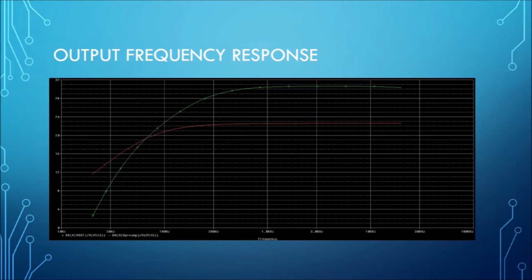As you can see, even though the amplification is very good and exactly where we wanted it to be, the frequency coverage isn't as good as we would like it to be. For instance, the negative 3 dB point seems to be right around 300 hertz, which is a little higher than we were hoping for. And this, in fact, will cause some issues, and we'll talk about it in a later stage.